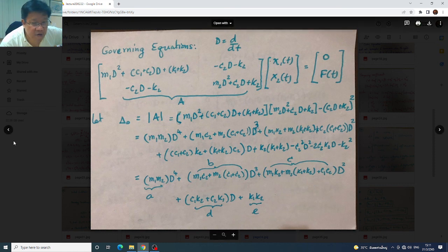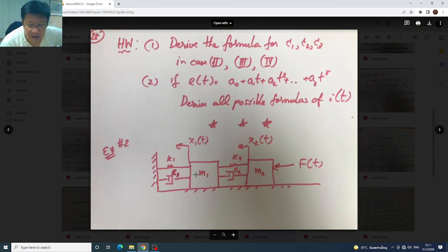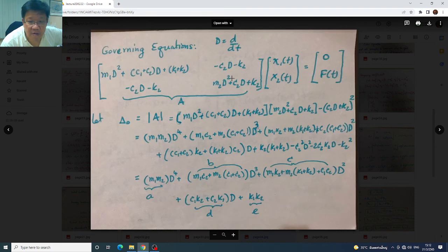In other words, the relative displacement when considering k1 and k2, when you look at m1, is x sub 1 minus x sub 2. And the relative displacement for m2, when you look at the free body diagram of m2, is x sub 2 minus x sub 1. So that is how this equation results, and you can rewrite it in matrix form as shown here.